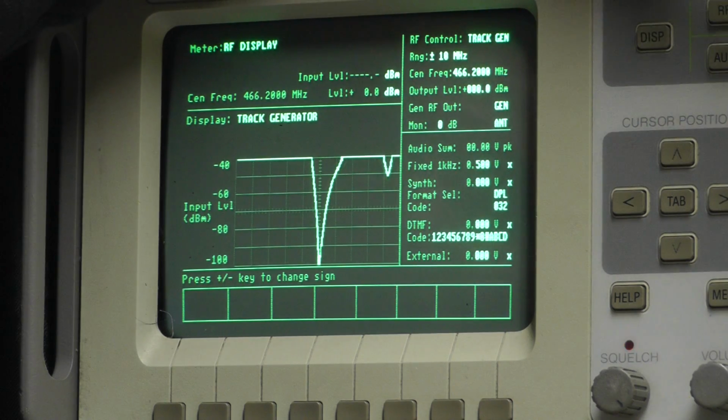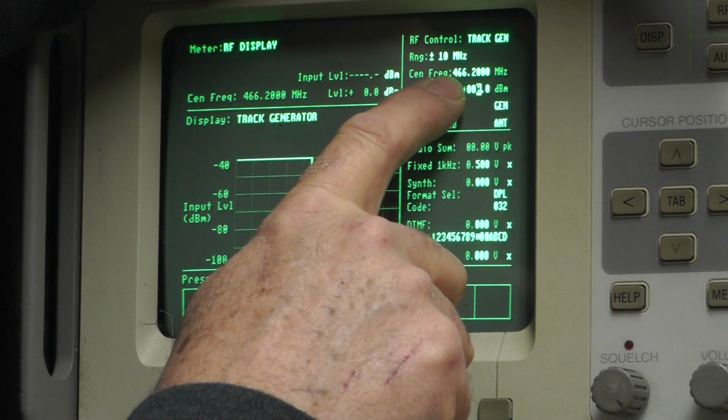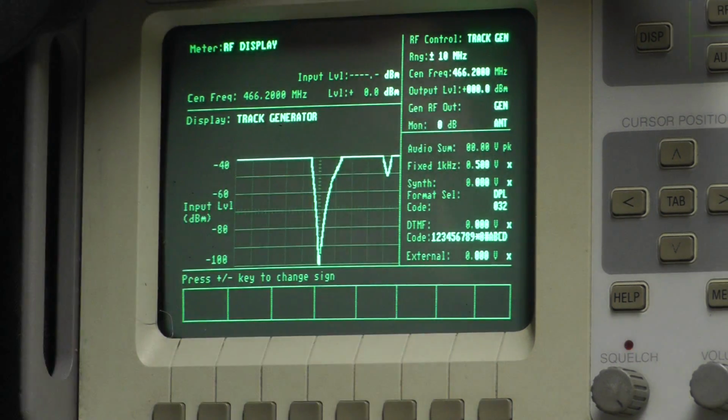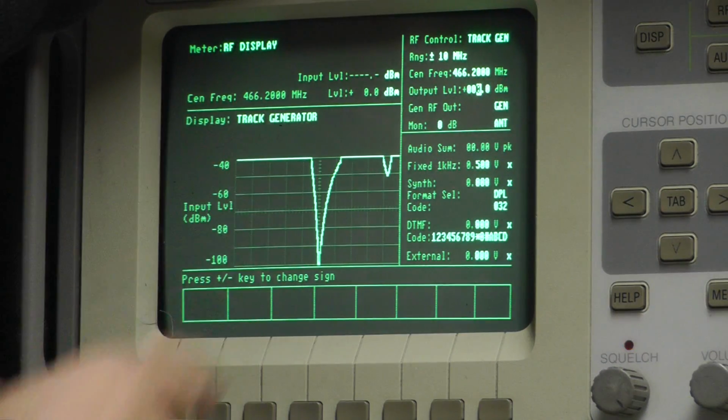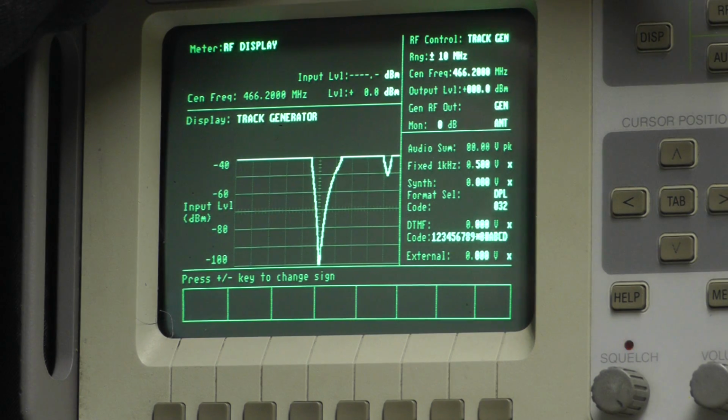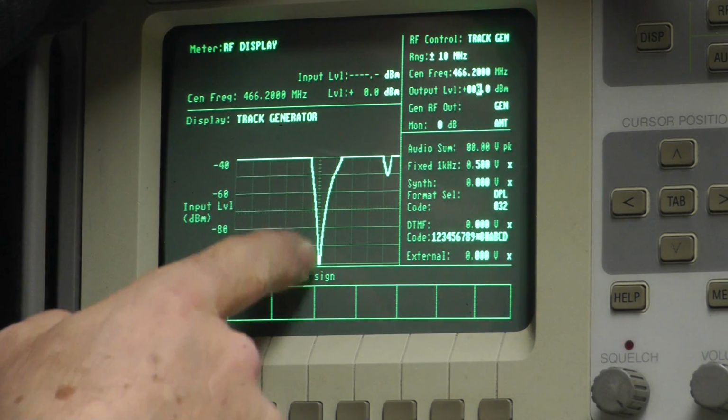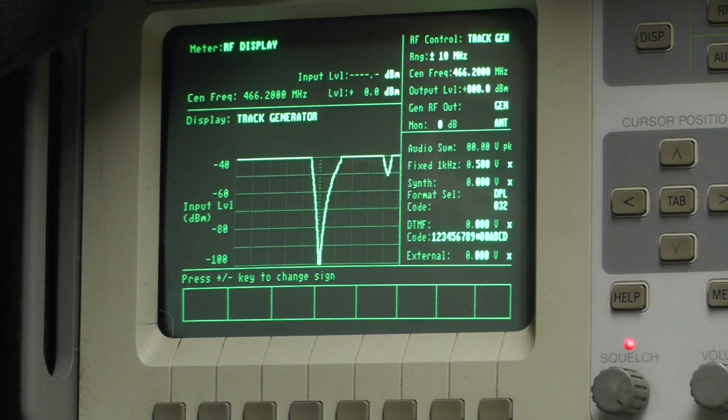And that's transmitting the receive frequency into the transmit side, detecting it at the antenna port, notching out any noise that might come out of that transmitter at the receive frequency. Now we're going to switch our cables over to do the other side.